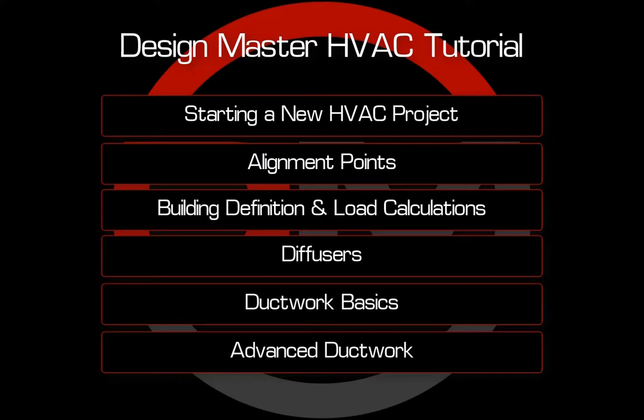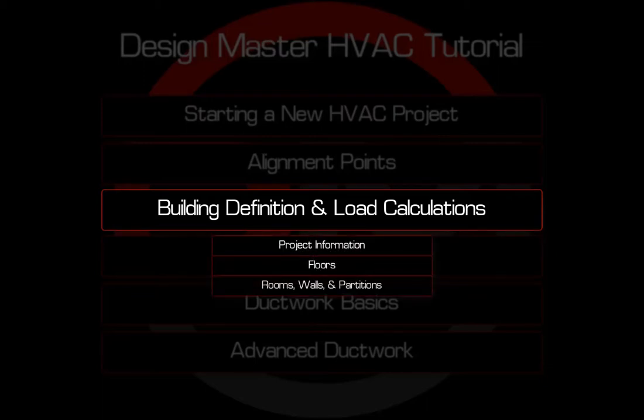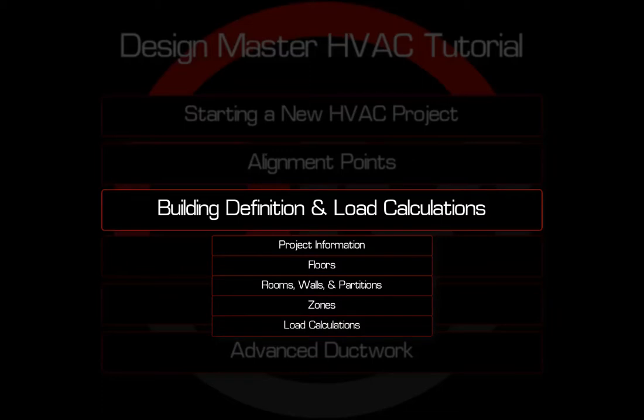This video covers defining your building and performing load calculations. Topics include setting project information, defining floors, creating rooms, walls, and partitions, assigning rooms to zones, viewing load calculations, and creating load calculation maps. Let's get started.